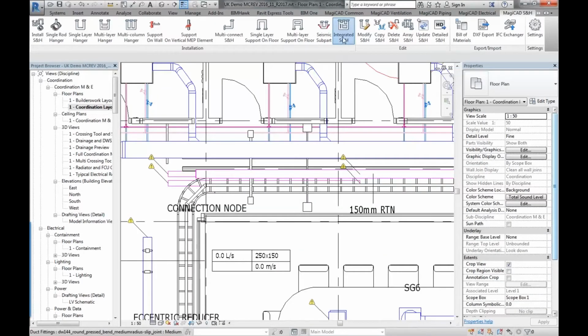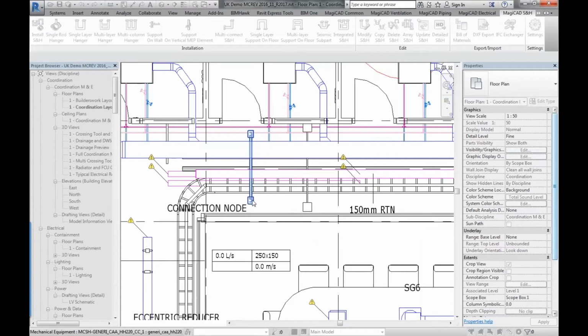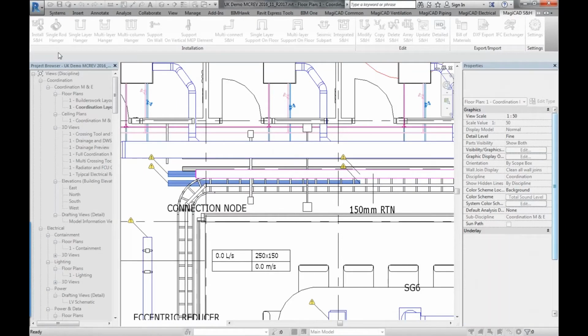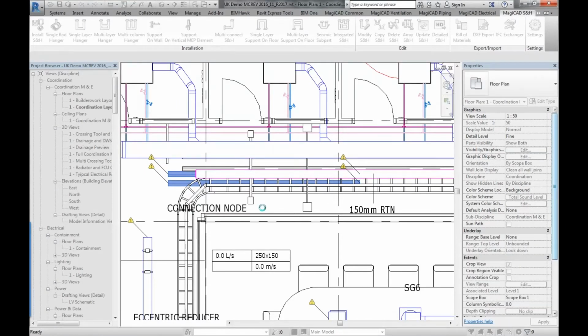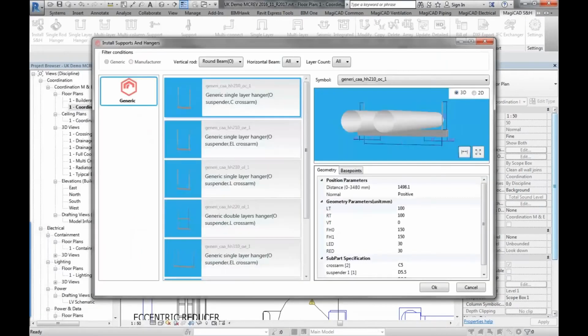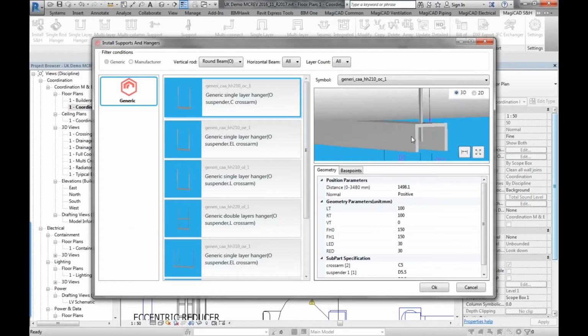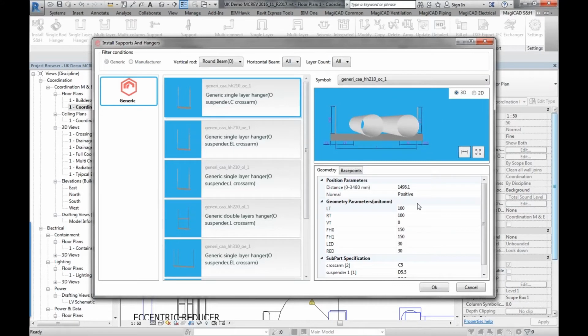So should I want to do that, I'll press integrated hanger. This time choose the hanger that I want to use to be the integrated hanger, and then choose the objects like these two ducts below it, and then now press finish. And now it will create a new hanger type like this, like it's got some drop rods onto a channel beam there. You can see like a unistrut type thing, and then I can choose, maybe if you want to change different dimensions if you so wish of that hanger.